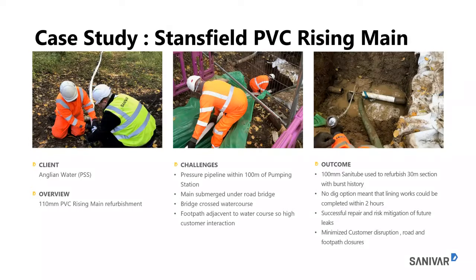which were then pieced up to the stub of the pre-existing PVC main. So that job, in terms of the lining scope of that work, was completed within about two hours total. Obviously, there was then time for pressure testing, backfilling, etc., but it substantively reduced the time on site and customer disruption.